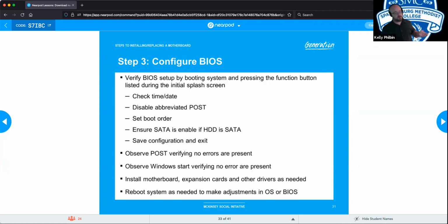Well, if you're putting in a new motherboard, I hope you're putting in a new CMOS battery. CMOS batteries are very cheap. They're like $1.50 a piece. A lot of techs will keep a stack of them in their tool bag just for quick use. And if ever you're going in and doing maintenance on a computer, like if you have to do anything major to it, go ahead and just swap out that CMOS battery. It just saves you time later. So I like that you brought that up. If you're doing normal preventative maintenance, you might just go ahead and swap it out to prevent the issue going forward, because the CMOS battery is typically only meant to last maybe one or two years.